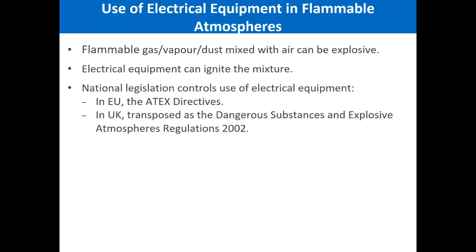Okay, there are something called the flammability limits. There is the lower flammability or lower explosive limit, and then there is the upper flammability or upper explosive limit. A fire will only take place if the concentration of the fuel in the air is within those ranges.